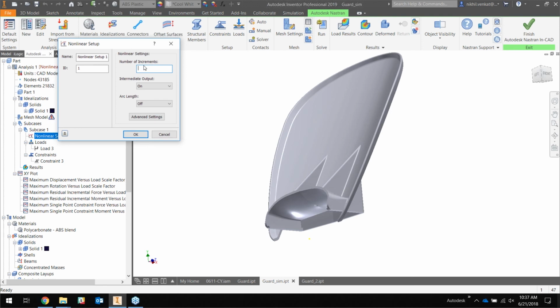You see results at the different time steps, so to speak. So even if you did leave it blank, it's just going to go for as long as it takes. If you do specify a value, it'll take that many increments, but it also solves based on sub increments. It'll still take the same number of iterations to solve. But the number of results that you see will be different, and that's the only thing.